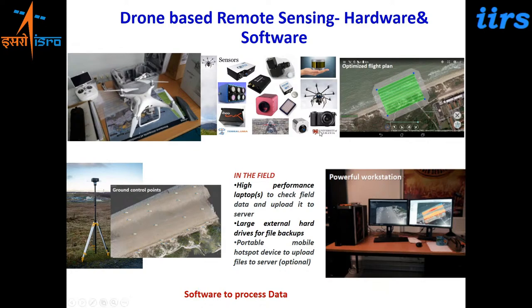Right? Then if you want to georeference the data, because the data which is collected will not have the geographic coordinates, you can collect GPS data, that is ground control points, using high-end DGPS equipment, and use this data to georeference the drone-based observations.